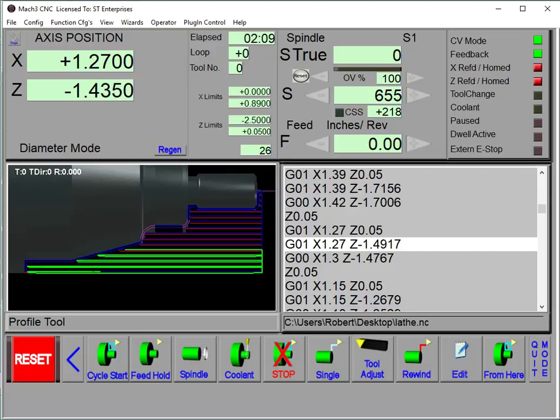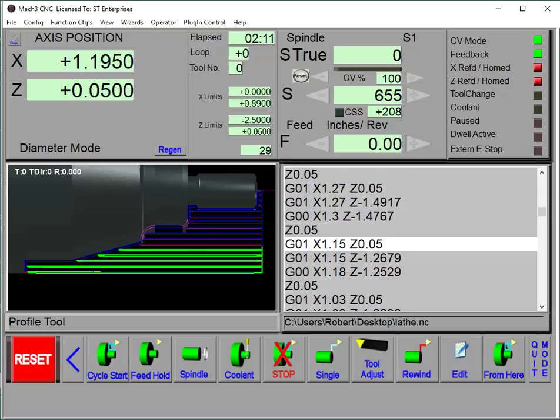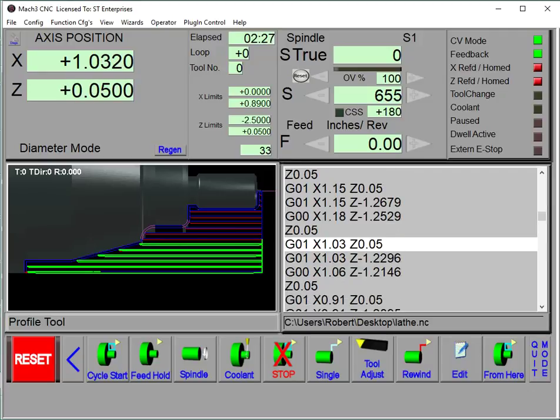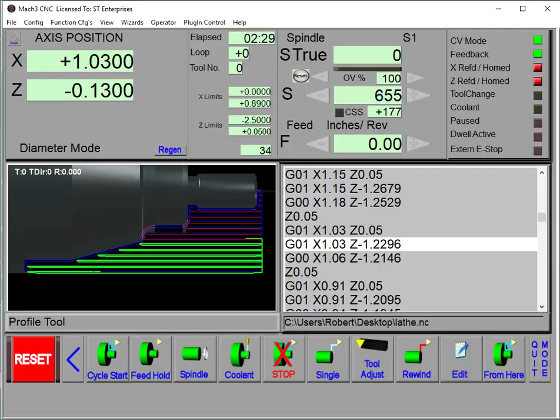So what we established here is, if I did the DXF right, it had finished the thread profile, well, thread diameter, and then you could use the Mach3 threading wizard to thread that diameter after you cut this.